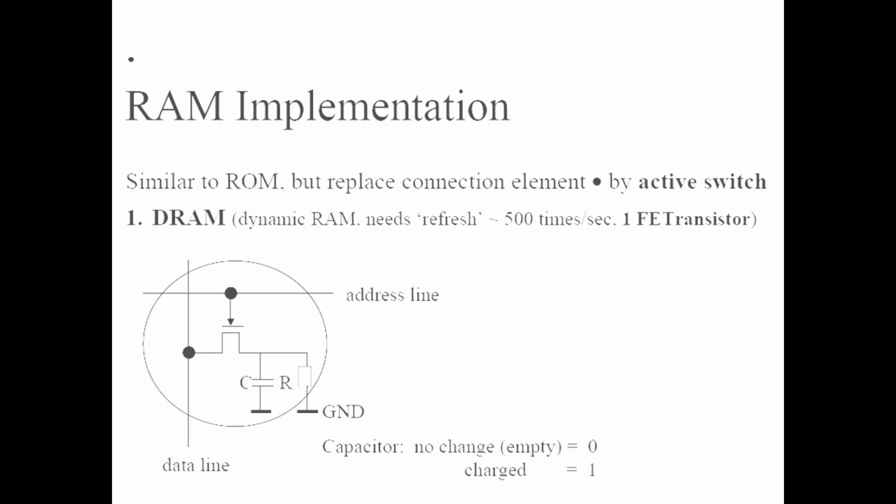As per the read operation, to read data, the transistor is turned on again. The charge stored in the capacitor is transferred to the bit line. The sense amplifier detects the charge and determines whether it represents a logic 1 or 0. Refresh operation. DRAM cells lose charge over time due to leakage. Periodic refresh cycles are required to restore the charge in the capacitors, ensuring data integrity.